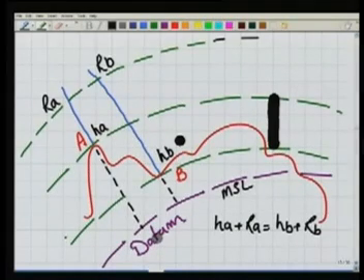Well, how to do that? At A I keep something over which I can take the measurements, and at B also I keep a similar thing, say a vertical rod and another vertical rod. In between, I establish one more surface which is parallel to my datum, that is, also an equipotential surface, along which I can bisect this rod and this rod. Wherever these rods are bisected, this height we say RA and this height we say RB.